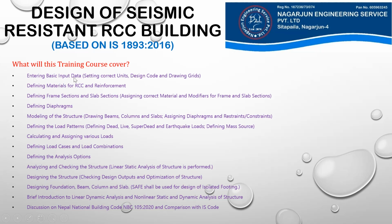The training course will include entering basic input data. That starts with setting correct units in our model, choosing the design code based on which we will be designing, and drawing the grids. We'll talk about drawing with grids later when the course actually begins. First, we will be defining the materials for RCC and reinforcement. What grade of concrete will we use, what grade of rebars will we be using, and then we'll define the frame sections and slab section.